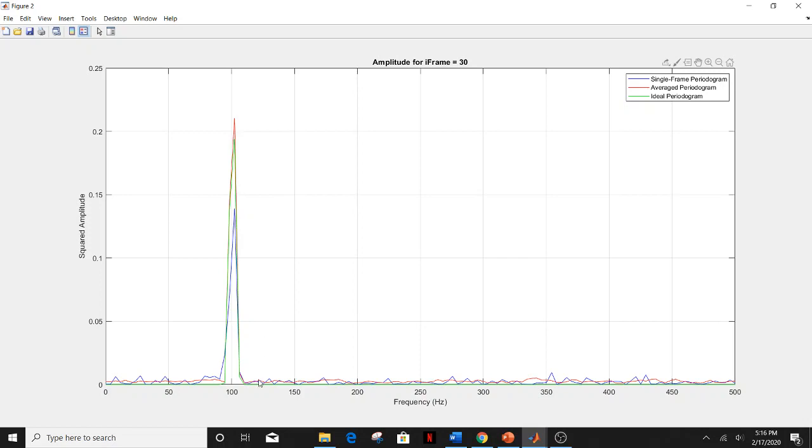More importantly, we don't really have as many spikes in these other frequency bands. It looks like we have a more constant noise level, which is exactly what noise is. Noise is infinite bandwidth if you're using Gaussian noise, so we have more of a flat spectrum here.